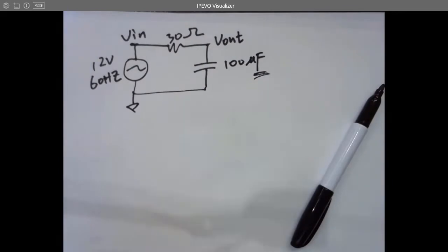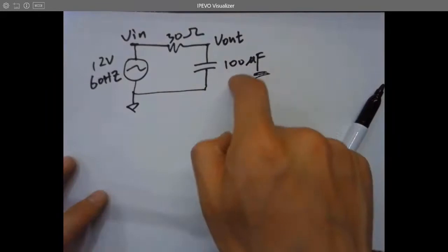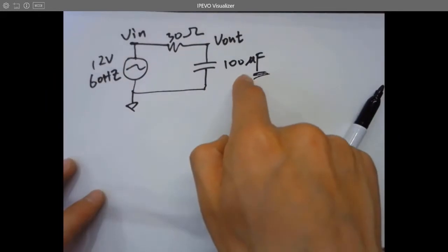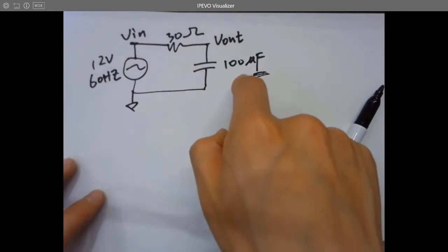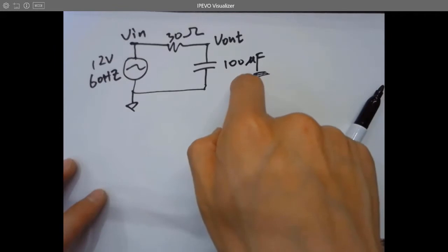So usually, if you grab a breadboard, you have all the wires and metals inside the board. If you measure the parasitic capacitance of the board, it's something around 20 picofarad, in the wire, in the cable, or anywhere. However, 100 microfarad compared with the pico is like 100 million times larger than that. It's a huge cap. Huge.